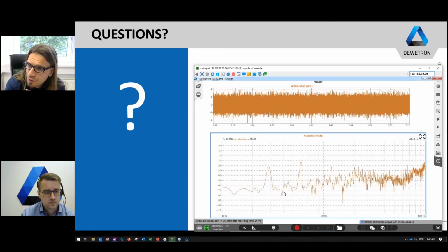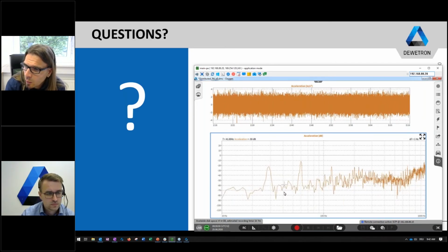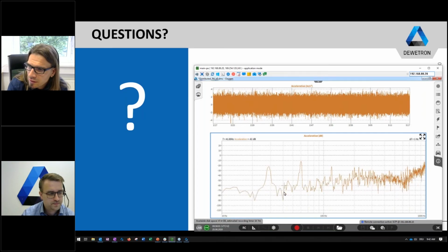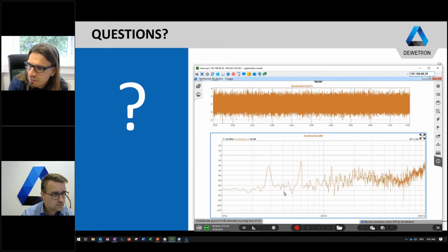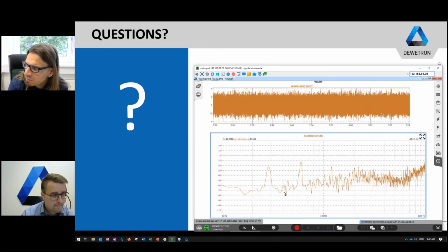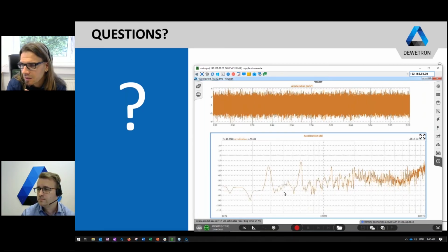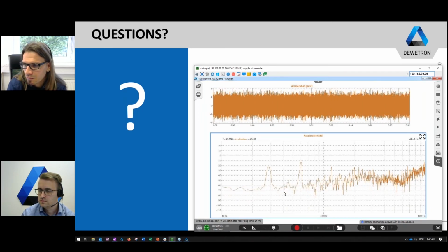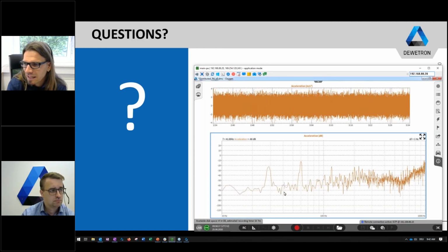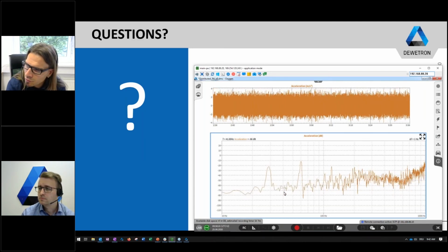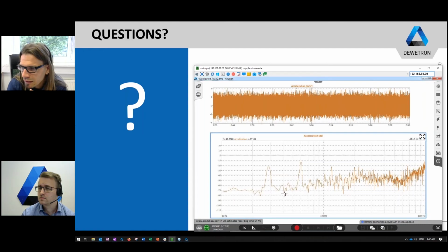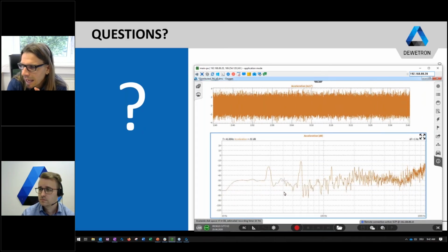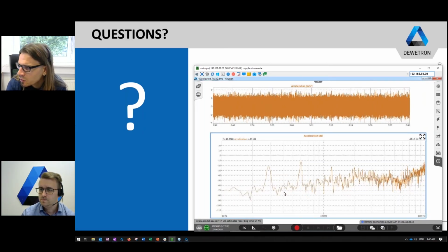That depends on the synchronization signal. When we use the internal sync source to synchronize several Tevatron devices, the absolute accuracy is plus minus 60 nanoseconds, plus 5 additional nanoseconds per meter. So when we have a synchronization cable length of approximately 8 meters, which should be realistic normally, we have an absolute accuracy of plus minus 100 nanoseconds.